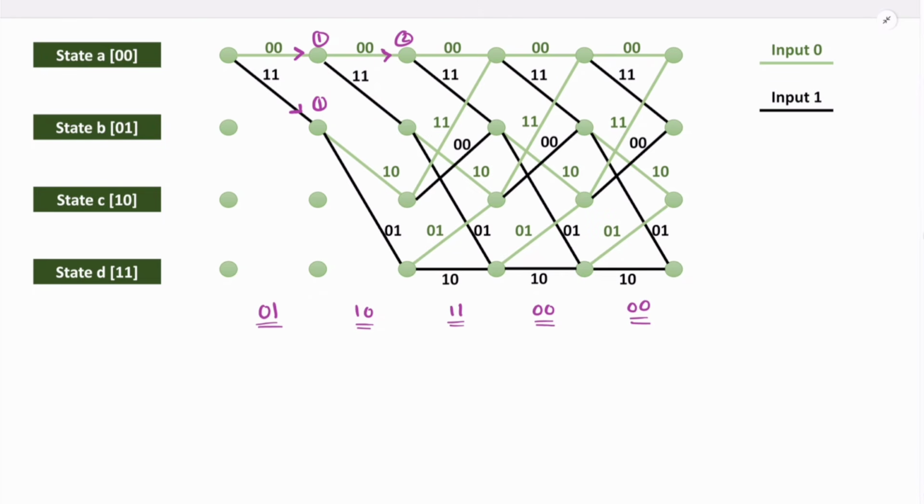And if you follow this path, and identify the difference between 1, 1 and 1, 0, then 1 bit difference is there. Previous weightage is 1. Current weightage is 1. So over here, there will be weightage of 2 by this path. Now, if you talk about this node, then that is connected over here.